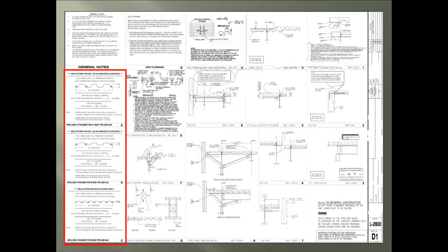As we move down the sheet, we find the next 3 details cover the attachments of the 3 different types of metal decking provided for the project. And notice the hat height which separates the different types. We now see a special note to the approver of these drawings, which usually is the design professional team.